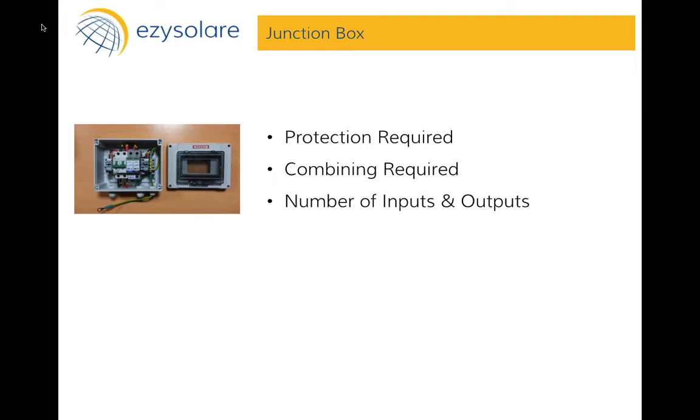An ESC type lightning arrestor, however, comes in different shapes and sizes. It can go up to 107 or 109 meters of protection as far as radius is concerned. And it obviously starts with a much smaller radius, right? So, whether you're going for conventional or an ESC type, you should ensure that the entire plant is completely covered as far as lightning arrestor protection is concerned. The make that we have available as of now is SGI when it comes to lightning arrestors.